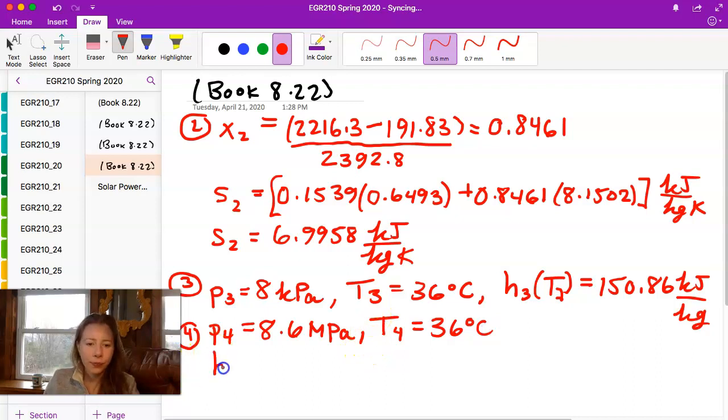So now we can get the isentropic enthalpy, which can be approximated by the following. And this is from an equation in your textbook. And I have posted a handout with all kinds of hints and equations for isentropic processes, for isentropic efficiencies, for the Rankine cycle. For next lecture, we're going to be looking at the Carnot cycle for vapor compression refrigeration systems. So that's all in a helpful handout that you can, of course, use on any exam, any quizzes, to help with your homework, to look at while you're going through these lectures. So that is a useful tool.